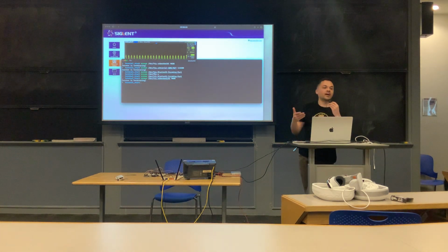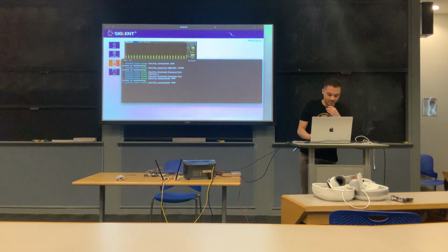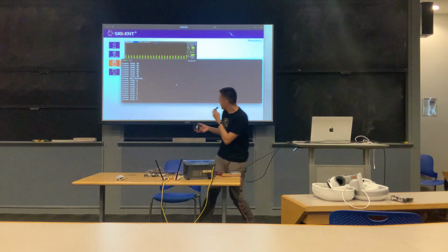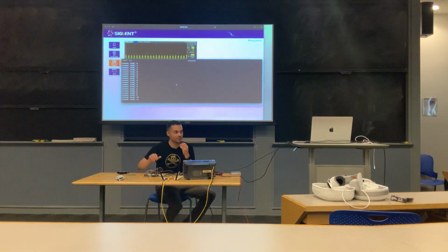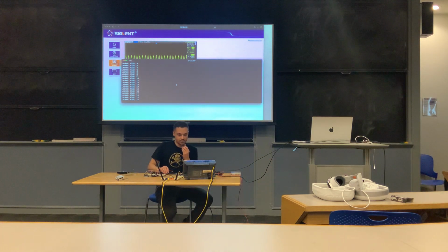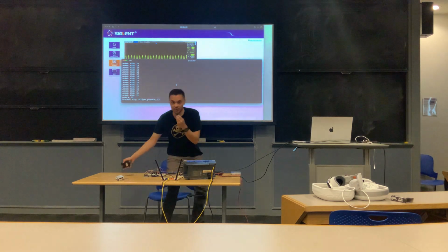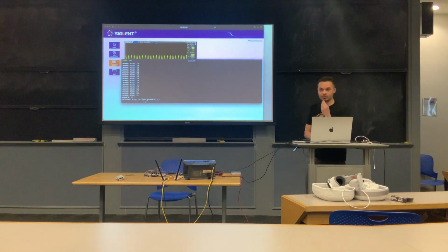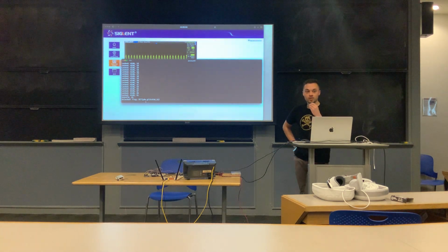And we'll define what I mean by freaks out in just a minute. So let's reattach here, and we'll see we boot up, and we'll go ahead and inject that pulse. So 5, 4, 3, 2, 1, and we did it. So we broke the loop. You can see we had some strange serial printing out some weird nonsense, and then we were able to break the loop. So we did it. We completely changed the control flow just by injecting some pulses into the clock signal on the chip. Pretty cool, huh?